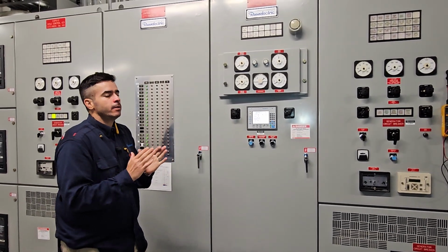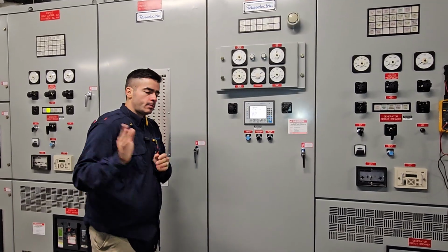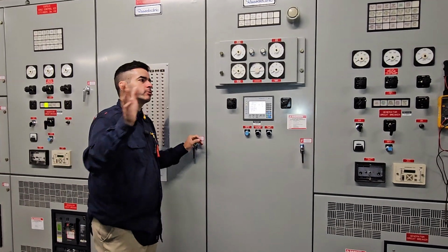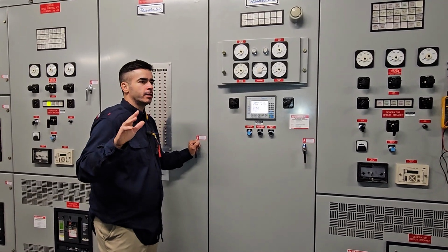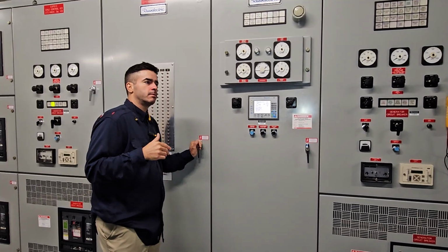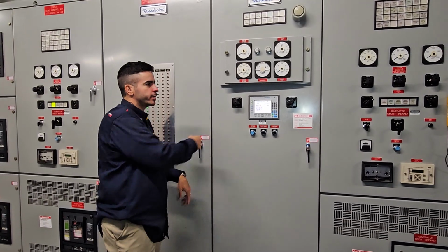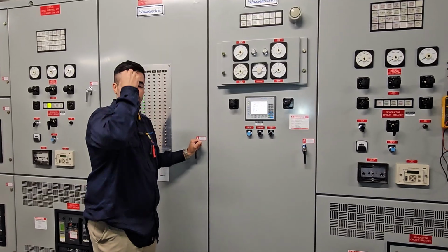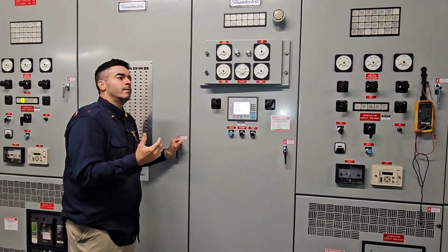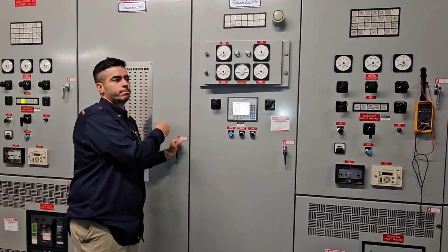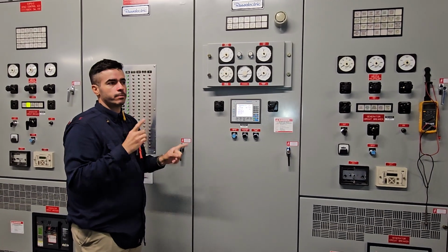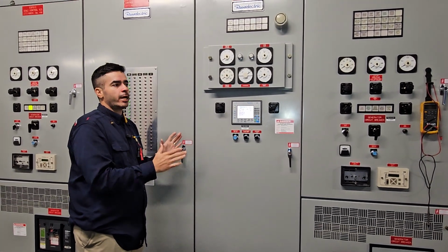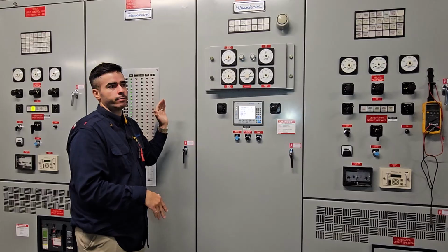The problem is people always say, oh, this is a priority one, it should transfer within 10 seconds, right? Like this is a life safety ATS. And then you put it on test, and it takes 5 minutes to transfer. It's like, what the hell? Well, you're putting it on test, you're not losing power. So you have both sources available. The 10 seconds rule applies when you lose power in the normal.